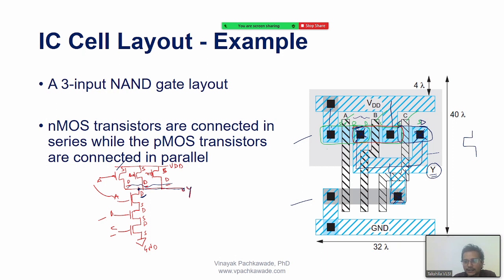First see, these drain contacts are made here. There is another contact here, right? So I got contacts with the drains of all the PMOS, and now I want the contact of metal with the drain of an NMOS. So here is that contact. You see, the total metal line is like this. Can you see now?